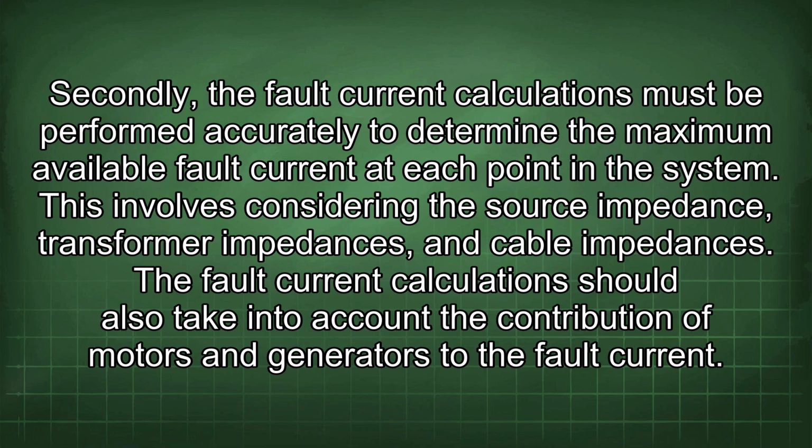This involves considering the source impedance, transformer impedances, and cable impedances. The fault current calculation should also take into account the contribution of motors and generators to the fault current.